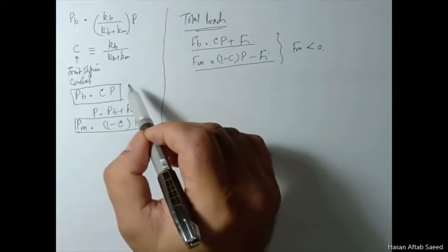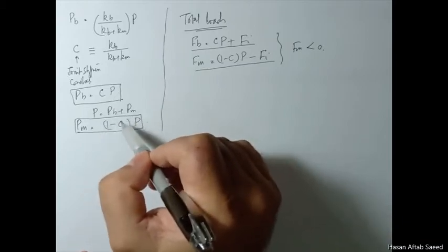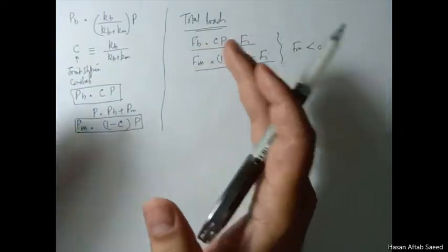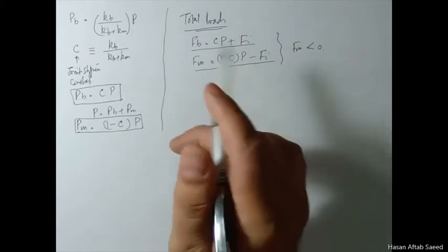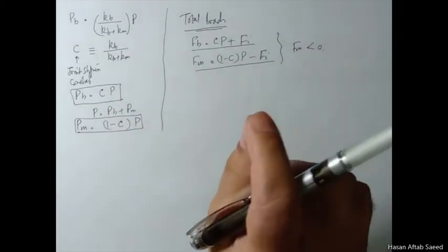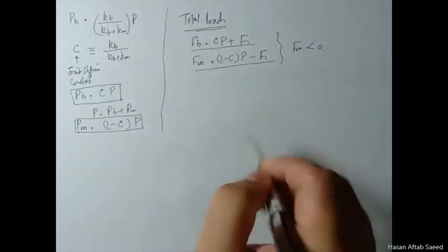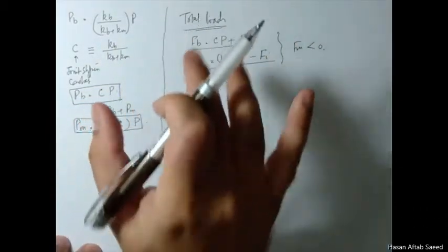The rest, 75 to 80%, goes to the members. That is, the members which are in compression are still in compression, but the compression is decreased. So that load goes there to decrease the compression. But as far as the increase of tension of the bolt is concerned, that is a very small portion of this external load.